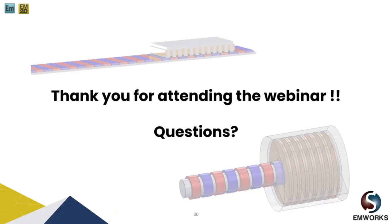So now you might get a thought that there could be a workaround so that we can use a rotary motor and convert it into linear motion by using some gear mechanism. Of course that is one option, but just remember that during the transmission of power from rotation to linear motion, again you'll have wear and tear in your gear arrangement and your system will become bulky, and also there will be some losses. So it's better to use a linear motor where you need a linear motion, where your application is related to linear motion.